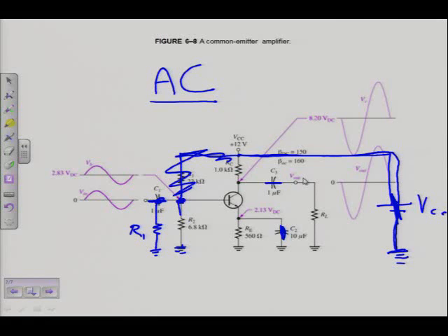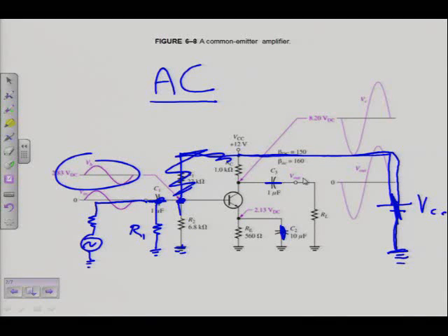Alright, let's just simplify. They've just drawn the input signal here. Let's just simplify the input part here as well. There's my input signal also to ground. That resistor is called RS. It doesn't stand for series resistor. It stands for the source. This is internal resistance. So when you see a circuit like this, don't go and look for a resistor of that value. It's the internal resistance of your source.